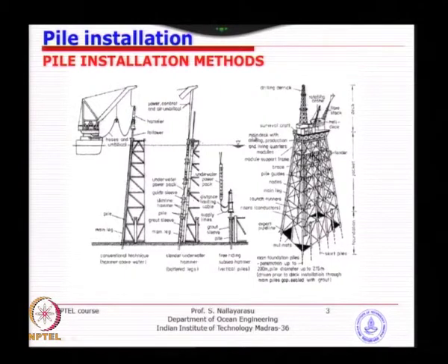Whereas here a diesel engine will not work because it is an underwater condition. So we may have to look for a hydraulic system where it will do exactly the same job, but with hydraulic machinery. So as long as you do not have a hydraulic system, you cannot think of going for a skirt pile of this kind. So what we do is a skirt pile of similar kind, but on the side.